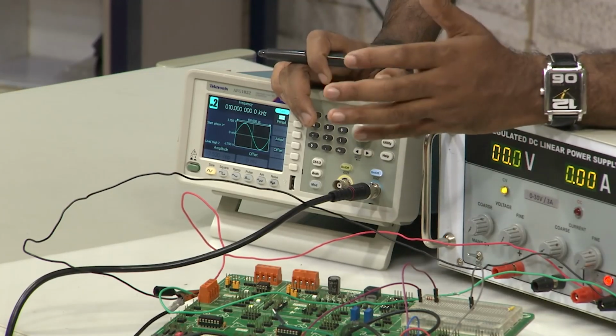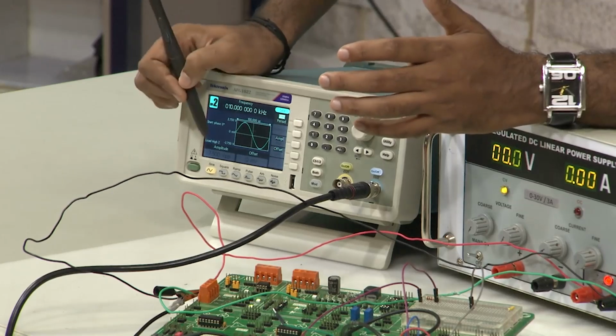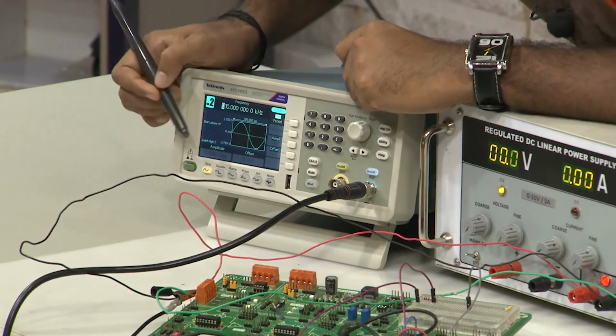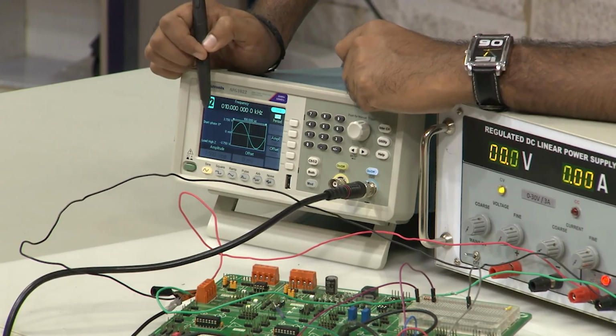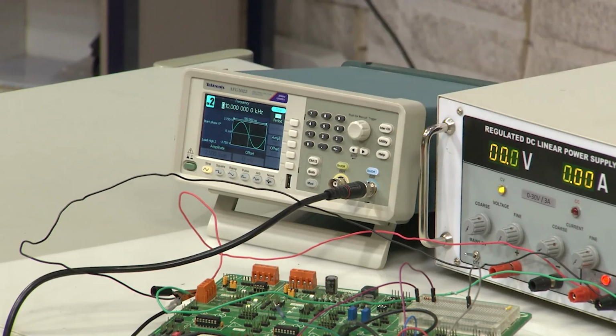Let us look at the function generator once quickly. So this is the function generator. Again we are giving the same 7.5 volt peak to peak input. We will start off with 10 kilohertz. For this circuit, our gain is 1, so faithful output is around 6.5 to 8 volt, or depending on your constraints, if you want to go down, around 6 volt is also fine. So till what frequency are you getting this faithful output voltage is what we have to see. The circuit connections remain the same for unity feedback, just like our previous experiment.